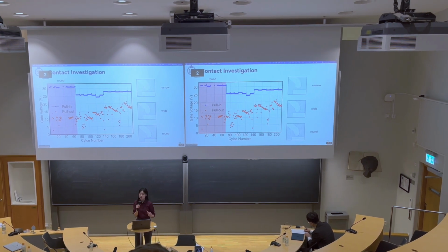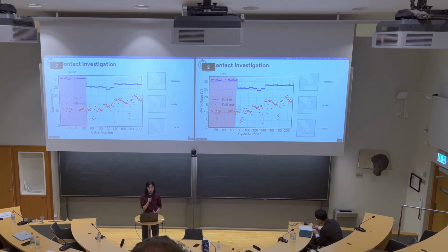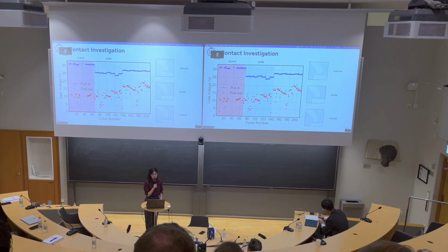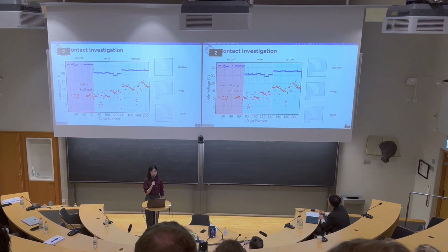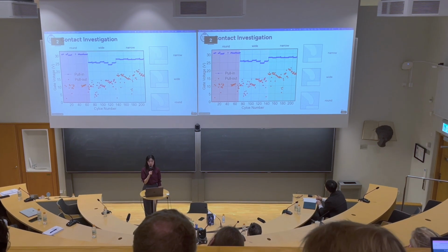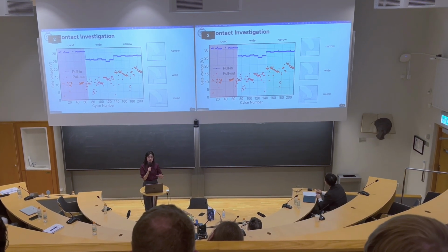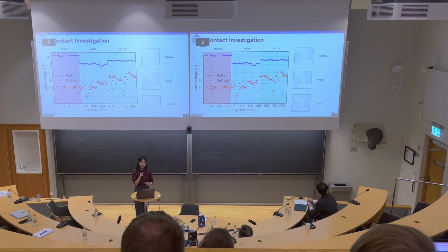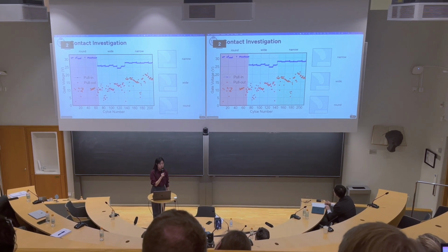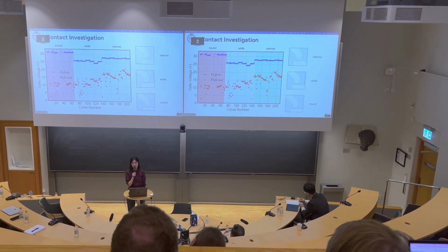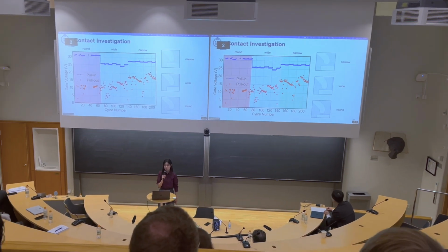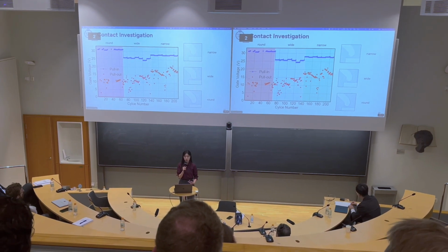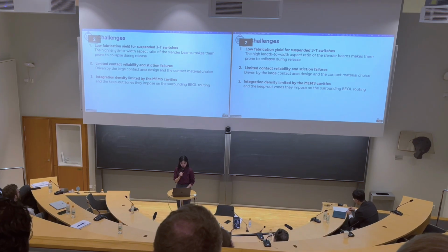And it also has a much higher hysteresis window. And for the other 2 groups, we see that they have a comparable pull-in voltage level. But for the narrow contact switch, we see a much better endurance through extended cycling, and also the hysteresis window is much smaller than the other 2 groups. So we finally took this ruthenium-coated narrow contact design for our work.